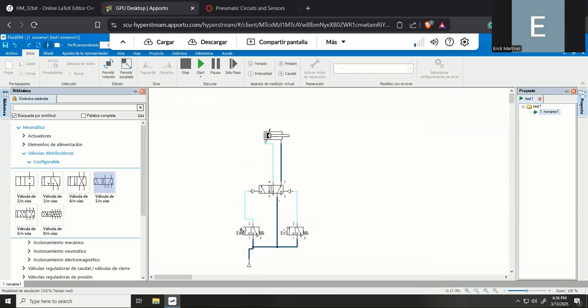But when I press this button at the left side, you will notice that I am allowing the airflow through this directional control valve, and then this directional control valve is controlling the left actuation mechanism of the 5-port directional control valve. And so the air is flowing from port number 1 to port number 4, okay?